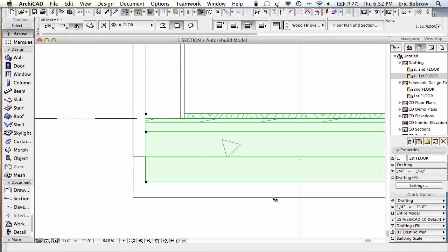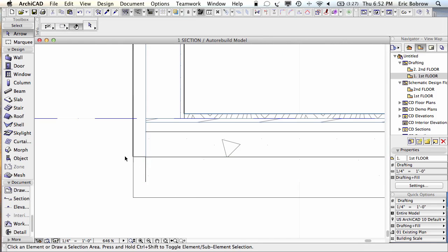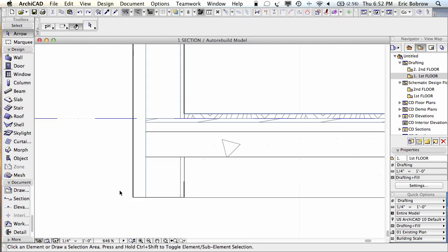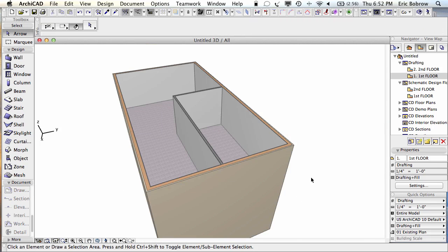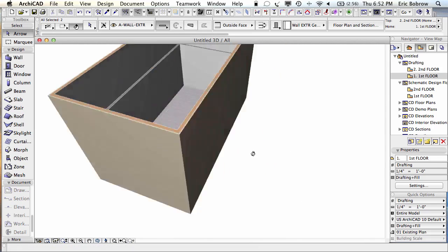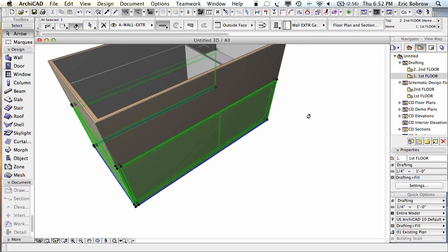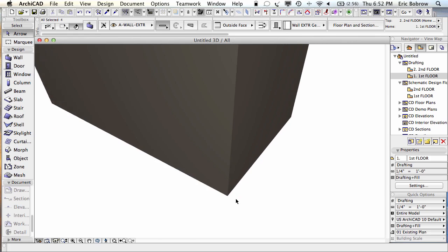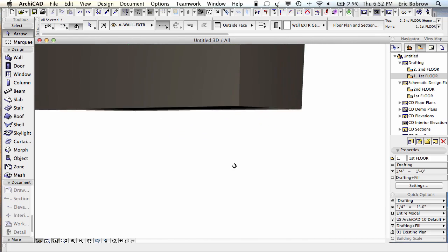Now in order to be able to clean this up fully, let's make all of these walls the same. So I'm going to move this wall back down, and then I'll go to the 3D, and we'll take all of the exterior walls here. Maybe I'll just rotate around, select them. So now I've got all 4 walls like that, and let me just pull them up.